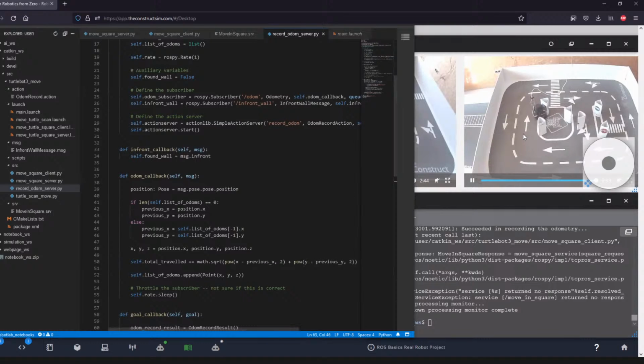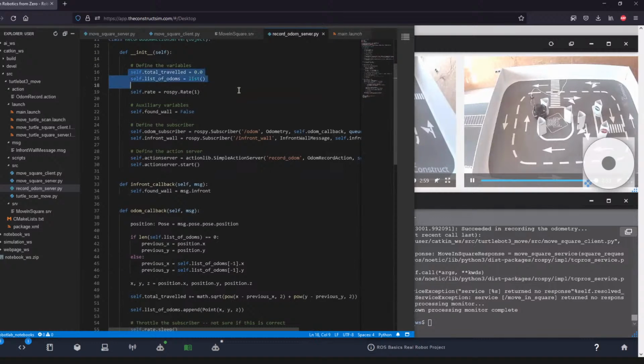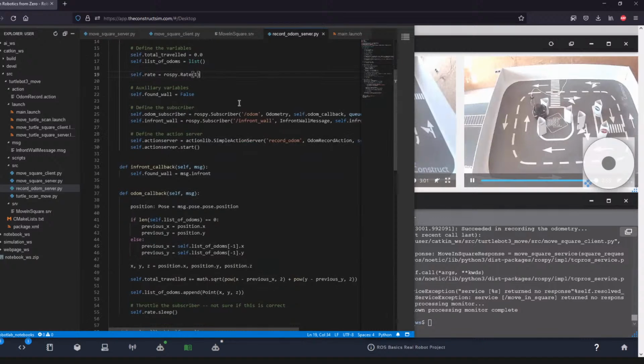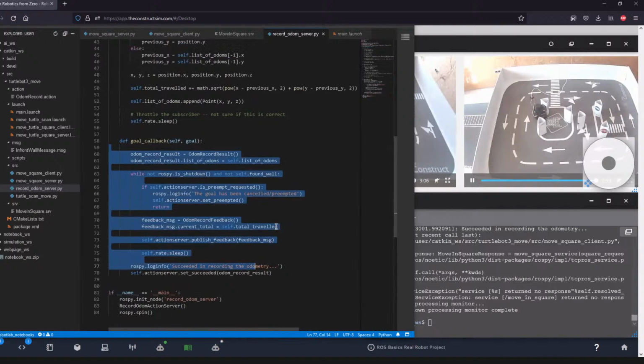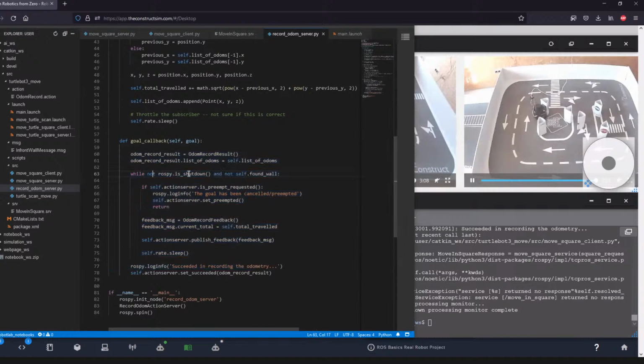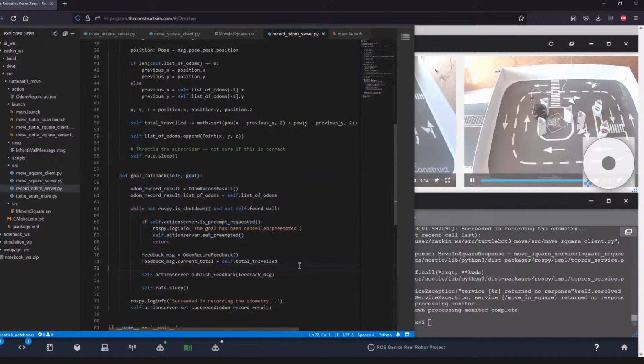It was a method from ROS that allowed you to join two different callbacks and have both messages in a single callback at the same frequency, and then it wouldn't have this issue. But in this case, this callback is an action callback, and this is a callback from a subscription, right? So we can't join them both.